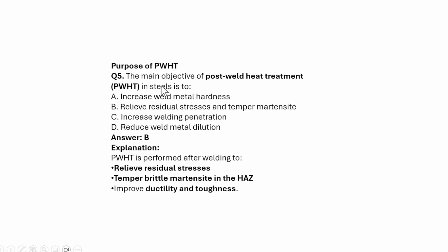Next is the purpose of the post weld heat treatment. What is the purpose? To increase the weld metal hardness, relieve the residual stresses and temper martensite, increase the welding penetration, or reduce the weld metal dilution. Options C and D are pre-welding conditions, so after post weld heat treatment, those will not be affected. Increase the weld metal hardness? No, heat treatment tries to reduce the residual stresses. Weld metal hardness we cannot increase by heat treatment. So the answer will be B.